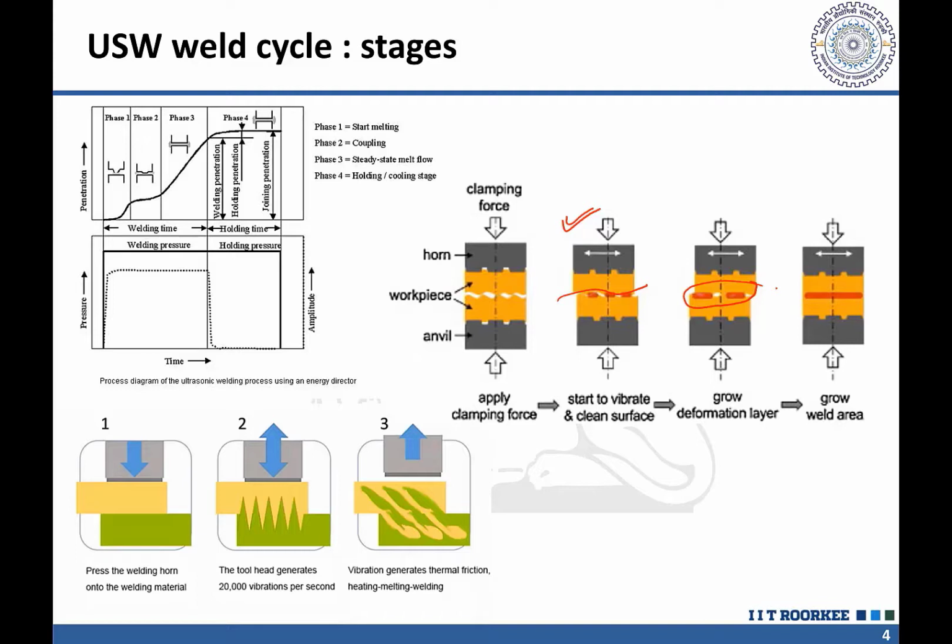They will be coming in close contact with each other, and so the metal to metal contact between the two components at the interface will be increasing. So you can see that the metallic intimacy zone will be growing gradually, and eventually we get the metallic intimacy between the two components. In this process we get a variety of situations.